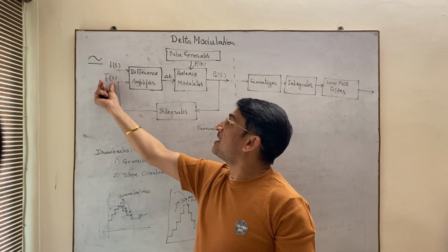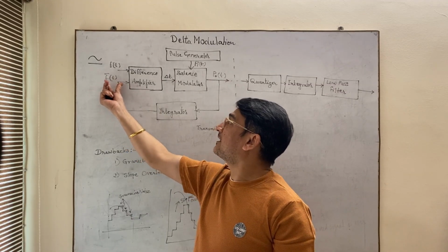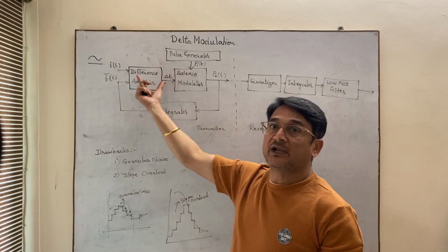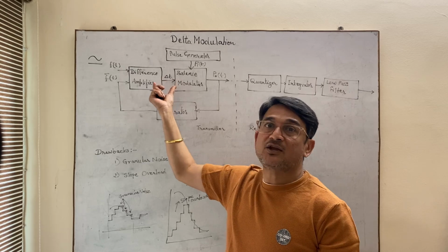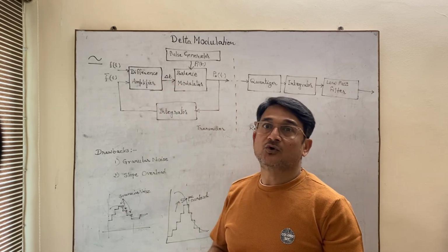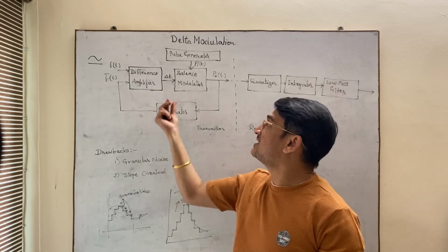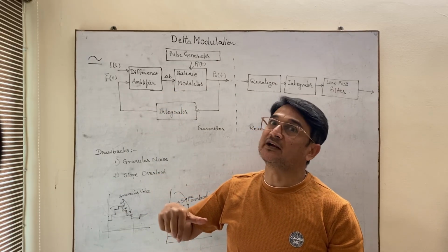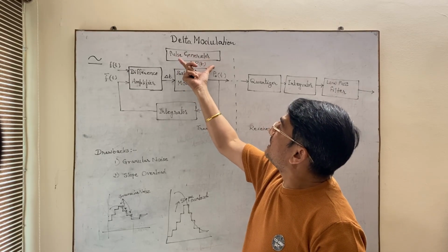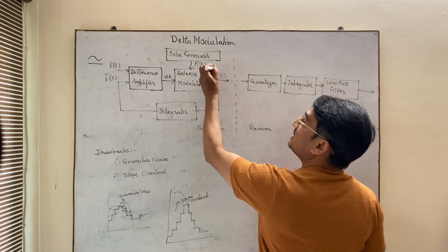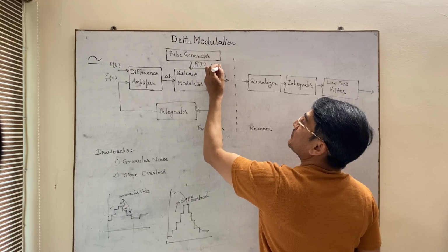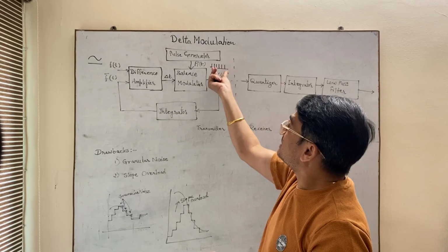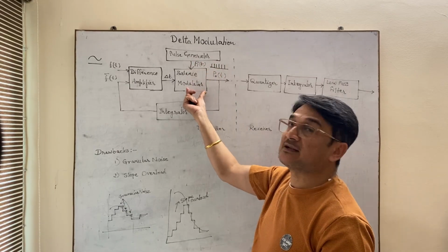Let us assume some arbitrary value according to this f(t). We are only interested in the polarity of the output. We are not interested in any values, we just need to know whether the output is positive or negative. Now this is a pulse generator, which continuously generates positive pulses. It produces continuous positive pulses to this balanced modulator.